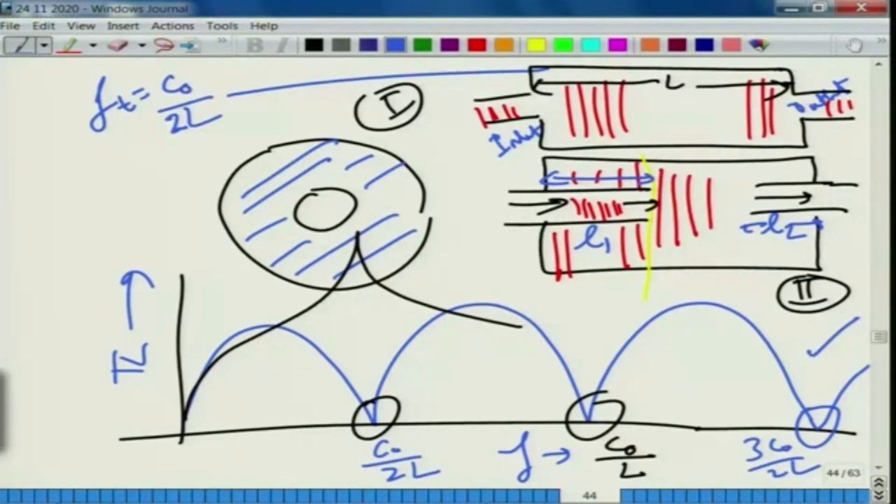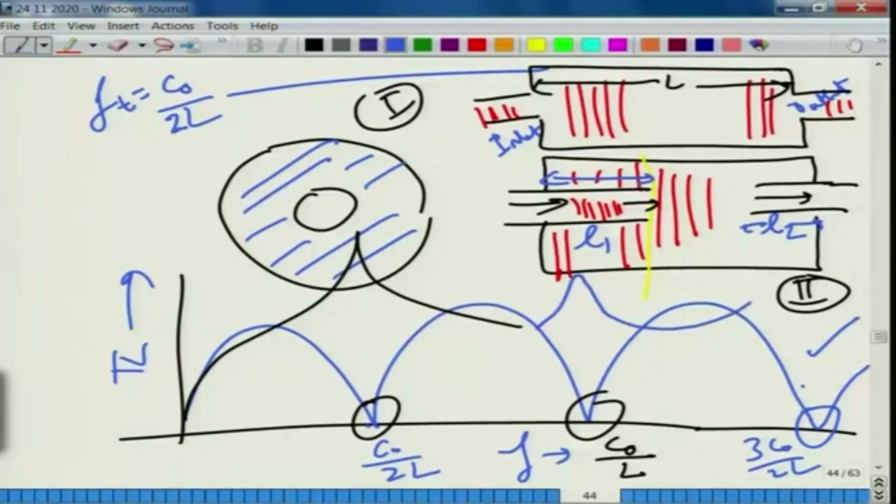But how far can we go with L by 2? We anticipate that the axial resonance trough and the peak frequencies are mutually coincident. So, the peak would hopefully cancel out the trough, the first one as well as the third one, that is here. So, we would get something like this and something like this. We will soon see, we will get the transfer matrices derived and show some results in MATLAB based on the planar wave theory. The whole idea behind this is to extend the attenuation performance to as high a frequency range as possible.